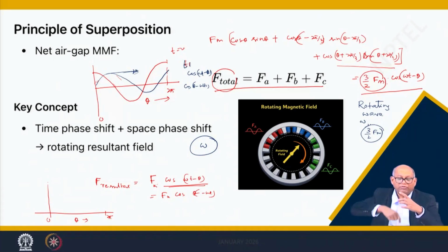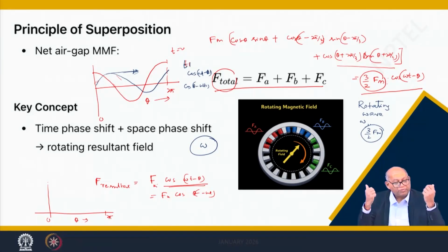So if the magnets are rotating, what happens to the rotor? If the rotor has conductors, the field will cut the conductors. In the rotor there will be a change in the flux linkages, lambda. So will there be voltage induced in the rotor or not? There will be voltage induced because this flux is cutting the rotor conductors. The rotor has a circuit, so it will make a current flow, and this current interacting with this field produces torque. That is the whole principle of the induction motor.